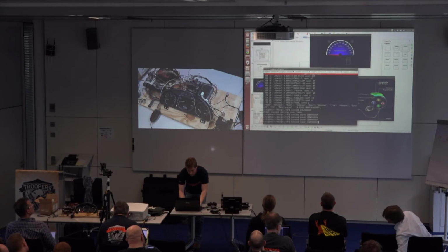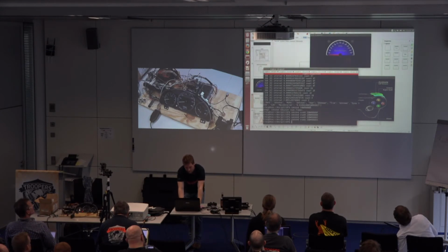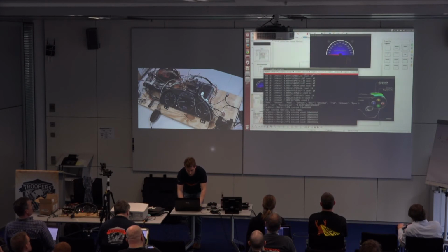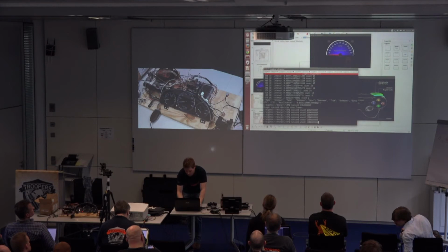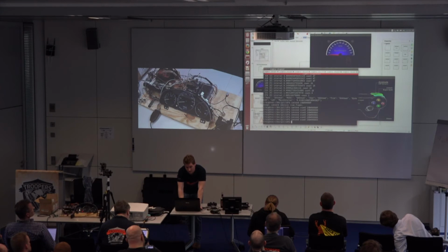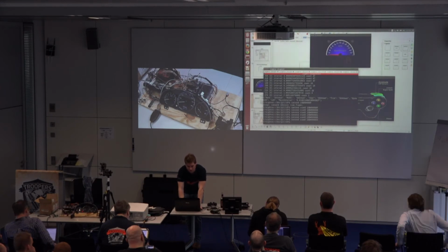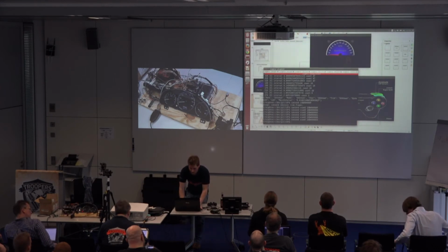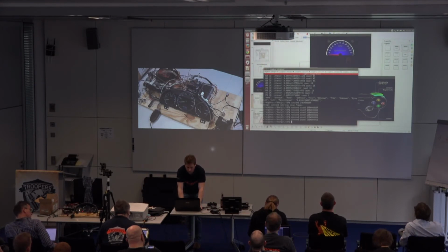This method works on real cars as well. Actually, the data you see in the background is from my Honda. Now if we were playing with this, if I just gave it a 1, we saw we unlocked 1 door. I'm going to lock them again, and then let's give it a 3 this time. You can see how they're using bits instead of bytes to control which door is getting unlocked. This is pretty common. Sometimes we'll see a whole separate byte used for a trunk, but not always. So something to be aware of when you're testing these.